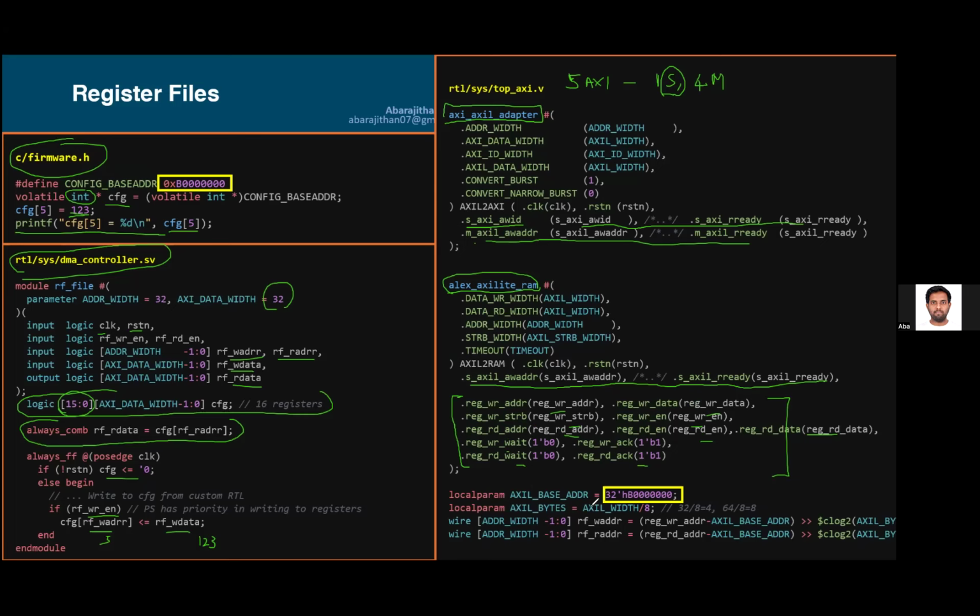And then here you have your base address, right? So we have the same base address as here. This is important; this is how you do the address mapping. If you use the Vivado address manager, it will do that part. But again, as I told you, you will have to write Tcl scripts and everything to make it reproducible. And the Tcl scripts are a bit finicky because when you go from one FPGA to another FPGA, if you have too many things, then you have too many edge cases. So we don't want that. We do support multiple FPGAs, but we keep the Tcl script as simple as possible.